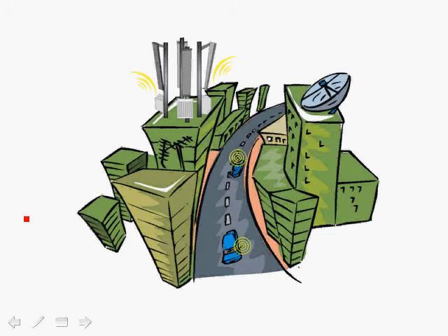In many cases, we have to deal with mobile communication systems in, again, situations where there may not be line of sight, and also the mobile is moving with a high velocity in which we have Doppler frequency spread and multipath fading that is very detrimental to the communication system. In this case, we have to actually use pilots in order to track the changing channel and also to track the changes due to Doppler in order to achieve reliable communications. The extra pilots, of course, introduce overhead and reduce the overall throughput.